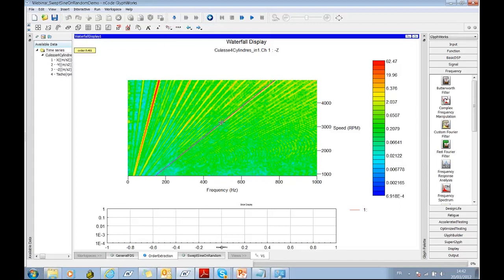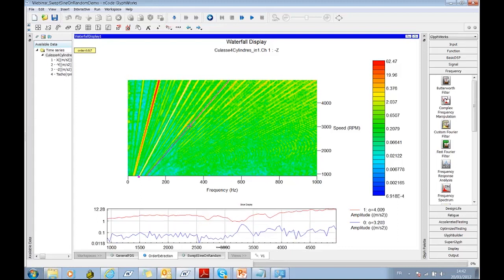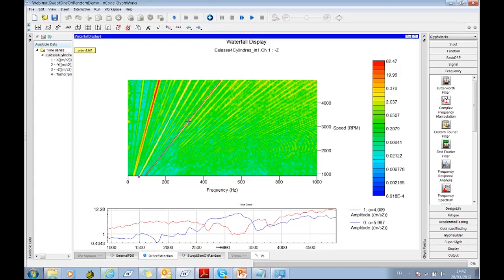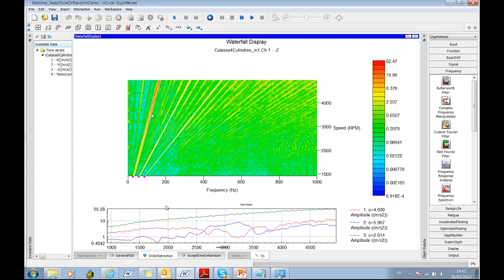So, for instance, let's display order 4. The order value is displayed on the top left-hand side of the plot. I hope you can see this little yellow post-it. Then order 6, for instance, right, and order 2, which is the predominant one. Order 2 is here, right. So we can overlay those orders, and here we see that the second order covers everything. So that's fine. That's the FFT-based order extraction.